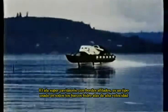We are lowering the pressure by dropping the water level above the foil by means of an upstream sluice gate. The cavity also grows when the water speed is increased. When the cavitating region extends beyond the trailing edge of the hydrofoil, we call the flow supercavitating. This sharp-edged foil is a type used on very high-speed hydrofoil boats, such as this 80-knot boat.